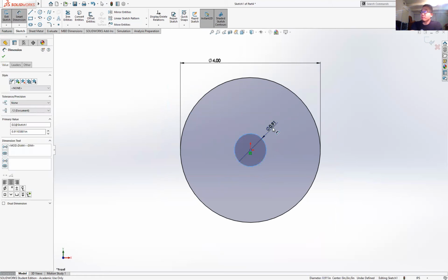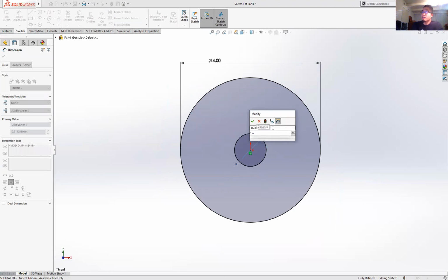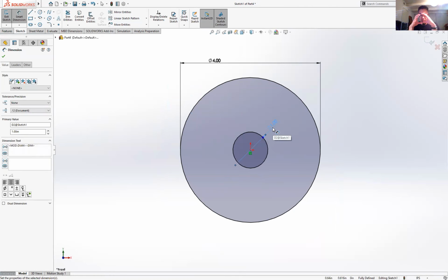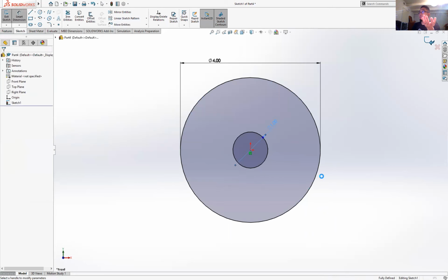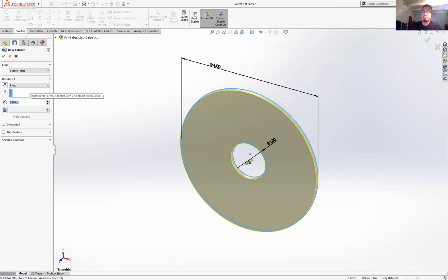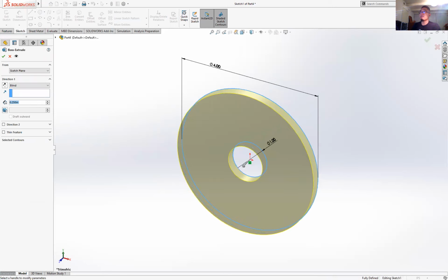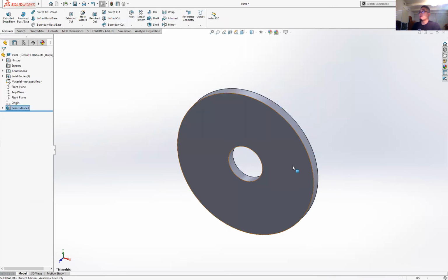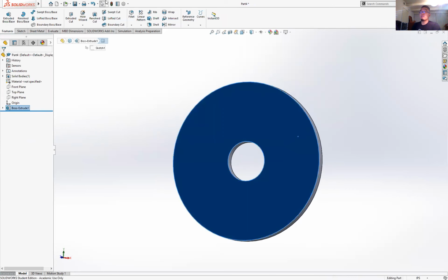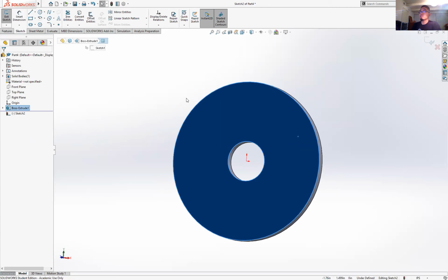So you could play with this tolerance, but if you put 1 inch, you might know that it's going to print a little bit tighter. So maybe you print it exactly 1 inch, and then when it prints tighter, you're going to be able to press fit it in. But you have to be careful. If it's too tight, you might crack your 3D print, right? So just be aware of that. Okay, so put that in, and I have a little plate. Maybe I make it, I don't know, 0.25 inches, something like that. If I wanted to put a feature on it, let's say something to hold my brushes in, I could click Extruded Base.